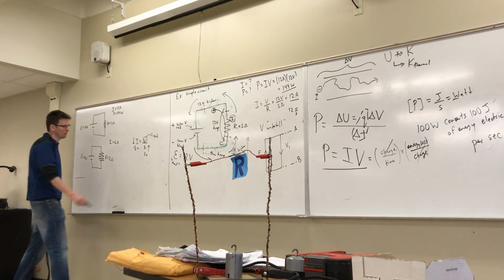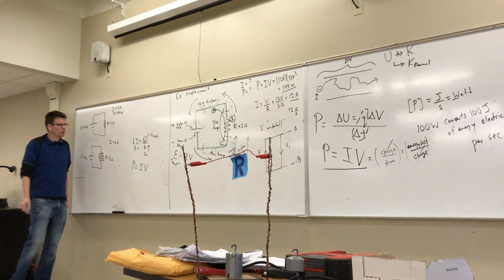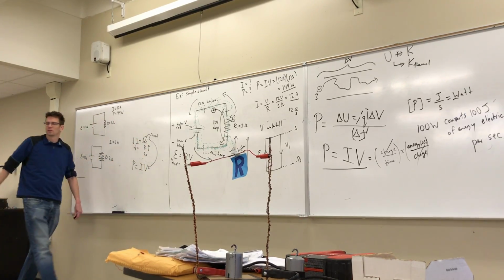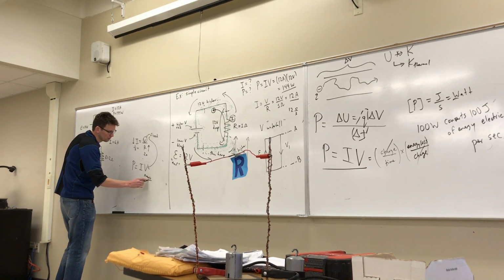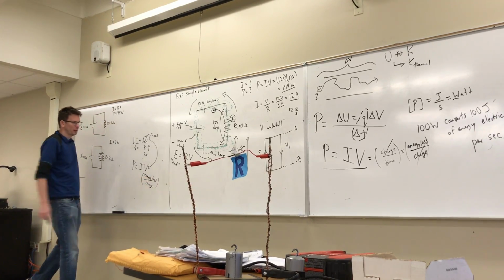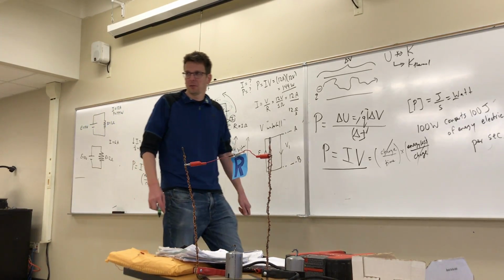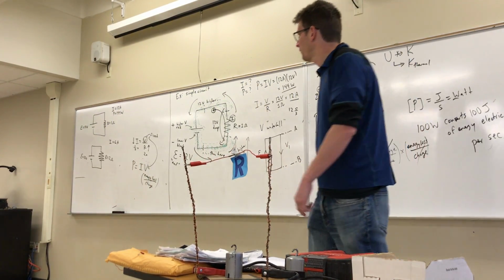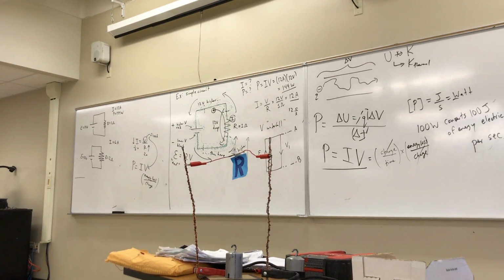So then, we look at the power. Again, the voltage is fixed. So remember what voltage is? This is the energy lost per charge. So every electron that flows through that resistor, or if you want to think of it as hypothetical pretend positive charge carriers, every single charge carrier that goes across there still loses the same amount of energy, but you just don't have as many of them, right?